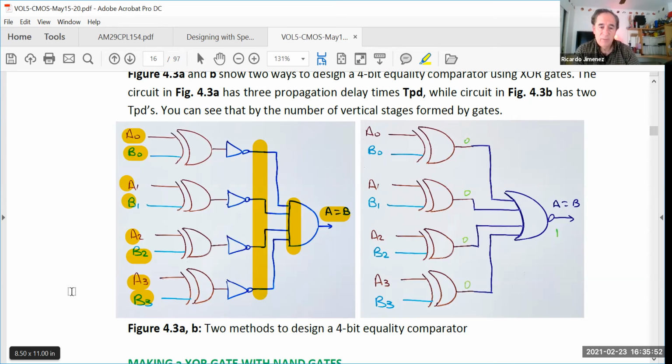That means that 240 will be different. And the speed is high. So in nanoseconds, you will know the result. So you want to know if A is equal to B, that's how you write it in assembly code or C language or any other language. And on the right side here, another way to do it is with the NOR gate. Because when you have 4 zeros, the NOR gate will respond. If I have 4 zeros, the output will be 1.